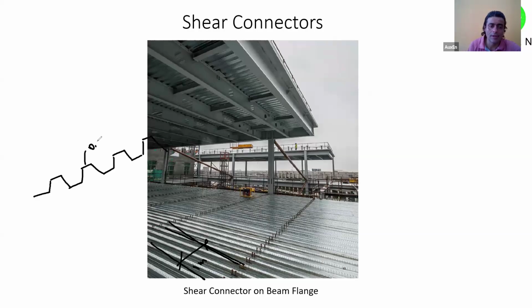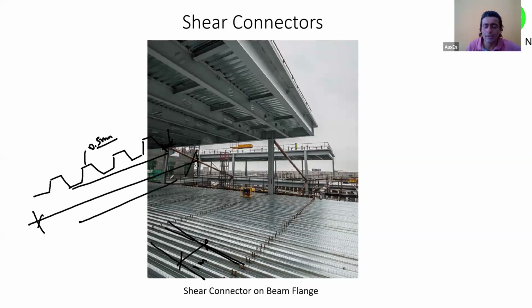Those are typically 0.5 mm thick profile sheets, and they have corrugations, and then you overlap it where it ends. So typically they come in whatever is the width, 1.2 meters or 1 meter, and then you overlap it. Similarly over here, these deck sheets will come in standard width, and then you will overlap it and lay it down. Understood? Okay.